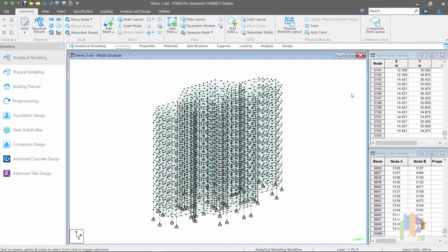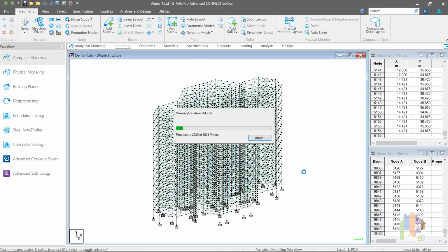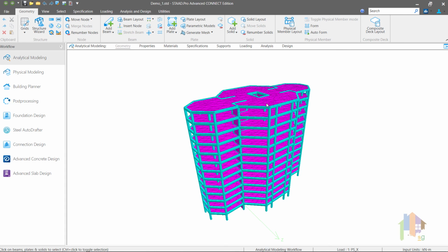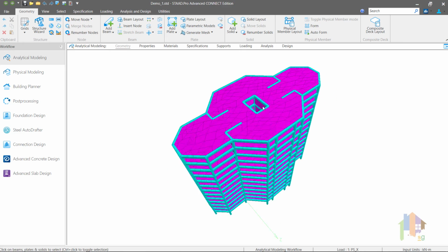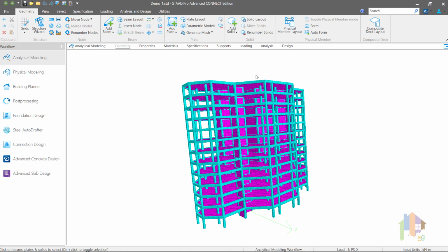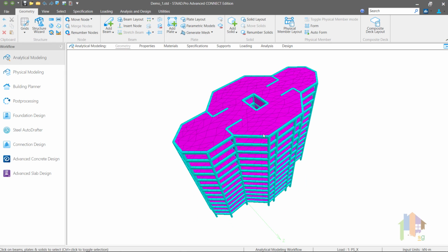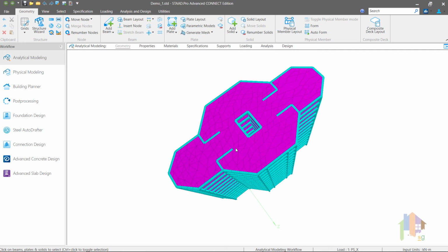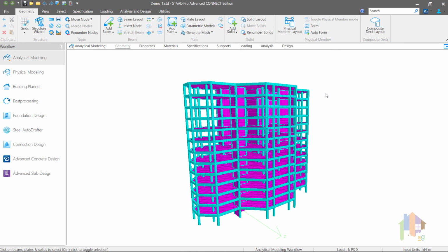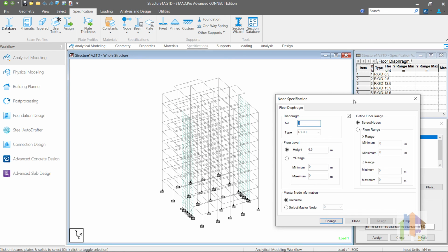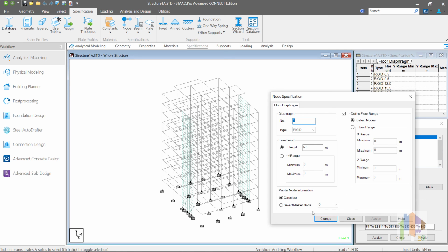In this context, I just want to add another point. If there is any cutout present in the slab, like a lift core or utility passage, or multiple connected towers with a central hollow core, you can duplicate this using the diaphragm command. You can select the nodes that are located on the floor slab, and ignore any node at the cutout. Then the program understands that there is no diaphragm present at that zone and accordingly neglects any mass defined at the hollow zone. This is very easy as there is no need to calculate the center of mass manually and everything is automated. You only need to define the floor level.